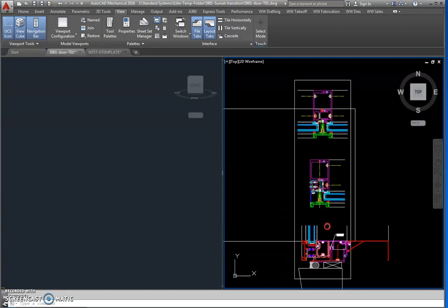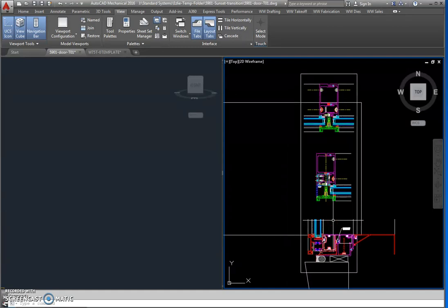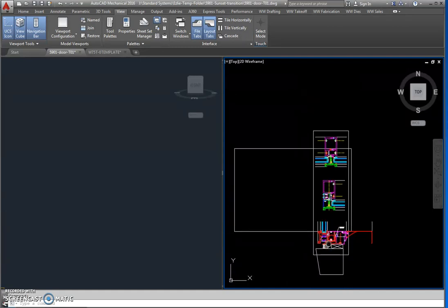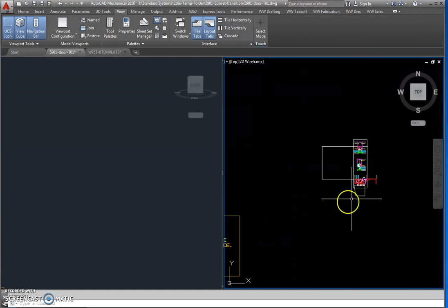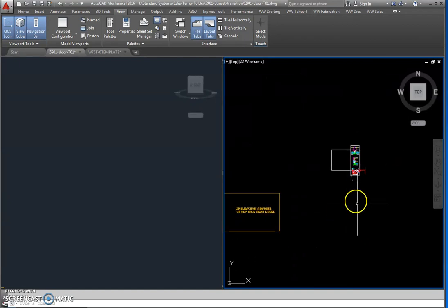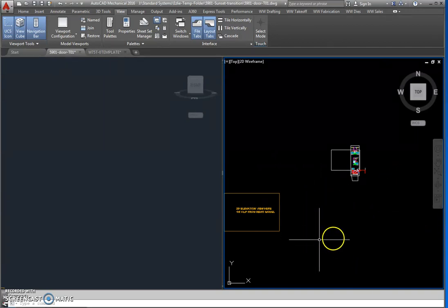And then the next thing is you're going to start modeling. So when we model here in Model Space, this whole area in Model Space is your working space. There's no exact science or location of where you're going to put it. And then you just modify the viewports accordingly when you're done with the model so that they appear in the viewports in Paperspace. So you'll see what I mean as we get going here.